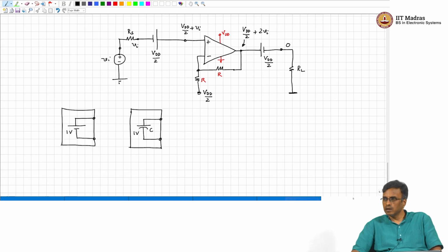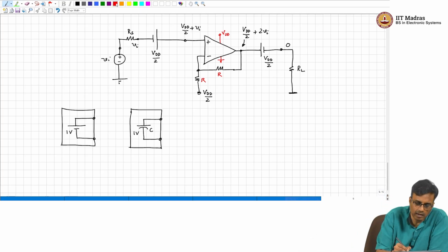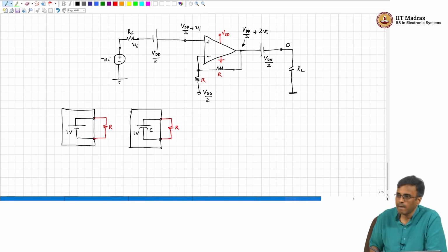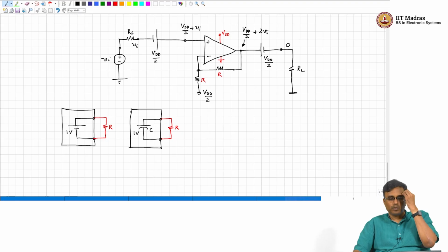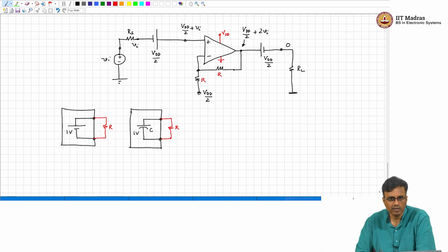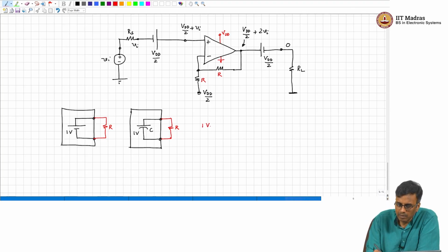Okay, you connect a resistor, the answer is okay. Let us try and connect a resistor R to both boxes. What happens? Very good. So, basically if you take a resistor and connect it across the 2 terminals, in the box in which there is a battery, the voltage across the resistor will remain at 1 volt and will remain constant, it will not change with time, all right. Whereas, the output of the other box will be 1 volt times e to the minus t by RC.